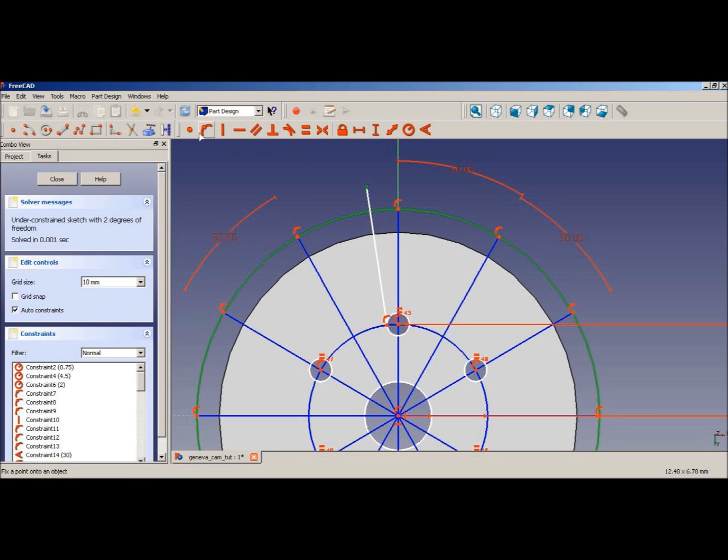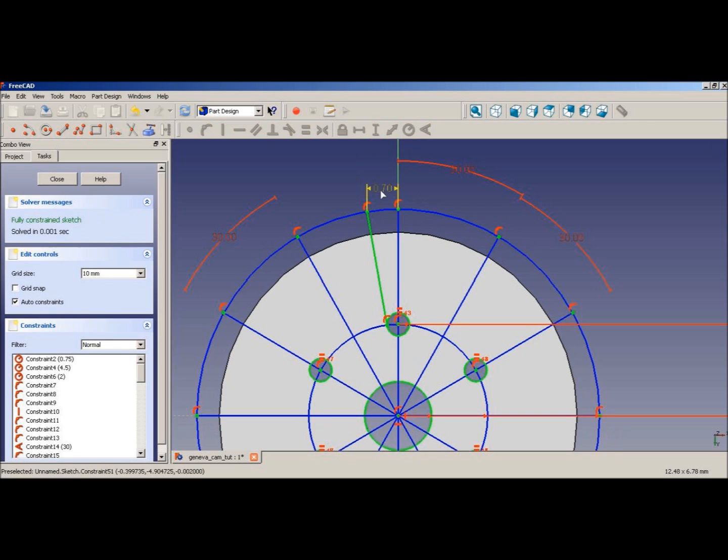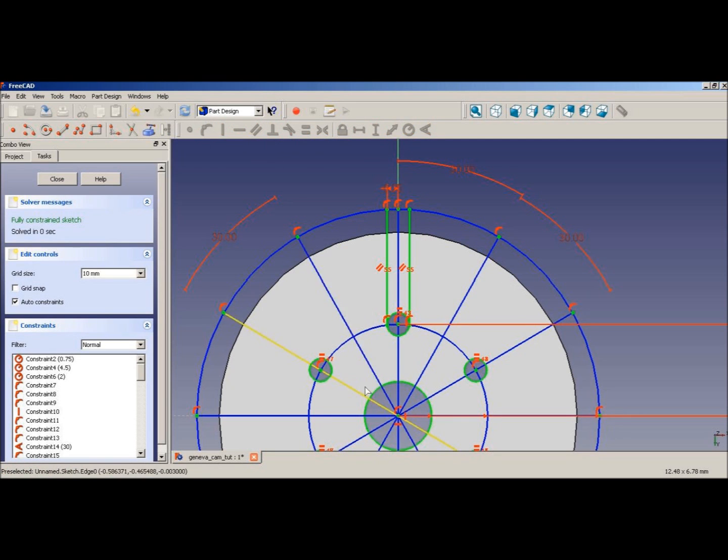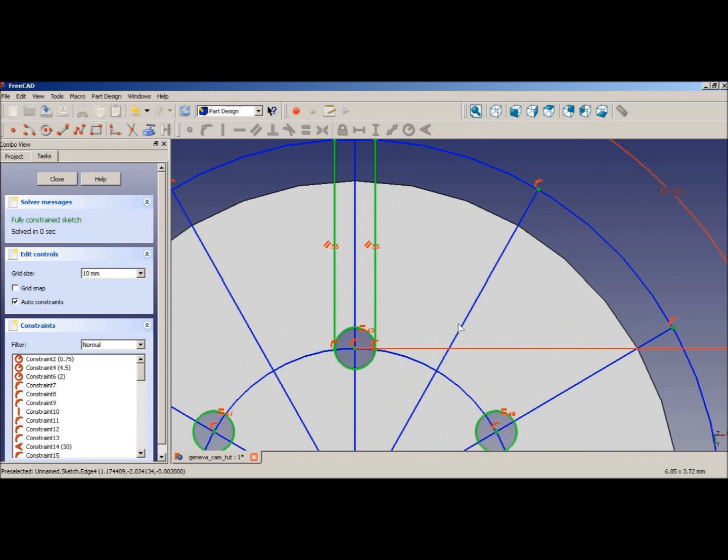But for all these, have a constraint on this outside circle, and there's a constraint of 0.25 for it being off circle. I'll make another line, set the constraint to the circle, there we go, and the constraint to the outside circle, and then we'll make these two lines parallel, give them a parallel constraint, there it is, and then set that constraint to the inside circle, and then we'll go in here and we'll snip out these insides.